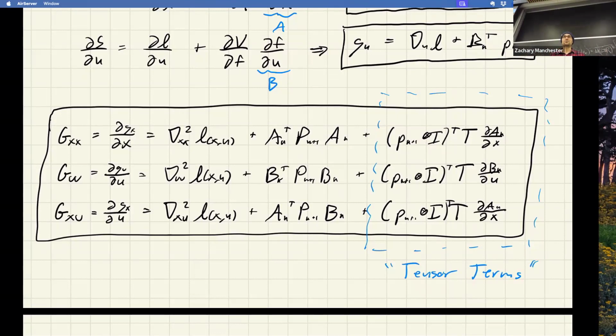Turns out Gauss-Newton DDP is what ILQR is. ILQR is the Gauss-Newton version without those terms. If you throw them in there, it's DDP. If you throw them out, it's what I would call Gauss-Newton. That's what people usually mean by ILQR. Although more often than not, people just throw those out all the time because they're a pain, and still call it DDP or ILQR or whatever. For all intents and purposes, people do whatever and call it whatever. But if you go back to the papers, those terms are in the DDP paper. They're not in the ILQR paper. But people basically use all those things interchangeably.